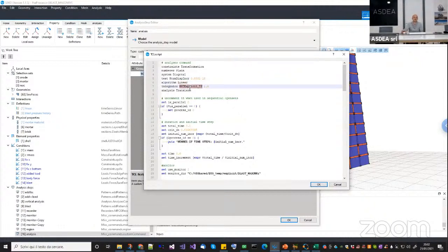And then you have to choose an explicit integration scheme. Now the default is the central difference, but I found that it doesn't work with element deletion because of the way it's implemented, so I use the HHT explicit. You can use the trapezoidal one or the one without trapezoidal, it's the same. It is important that this value is bounded between 0.67 to 1. 1 means no numerical damping, 0.67 is the maximum numerical damping. Keep in mind that if you use numerical damping, you have to further decrease the time step, and I don't want to do that, so I don't want any numerical damping here.